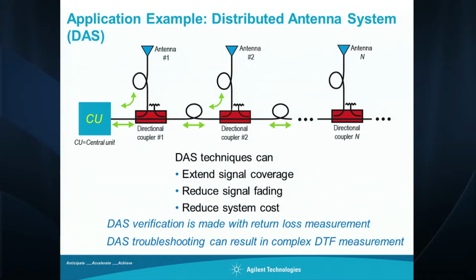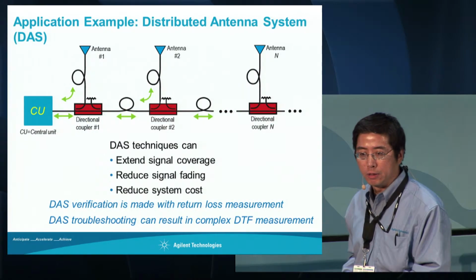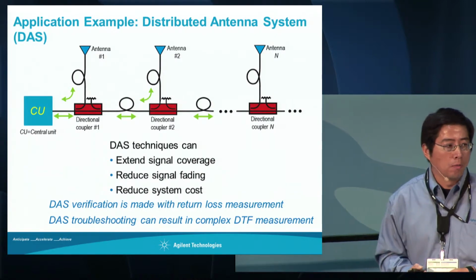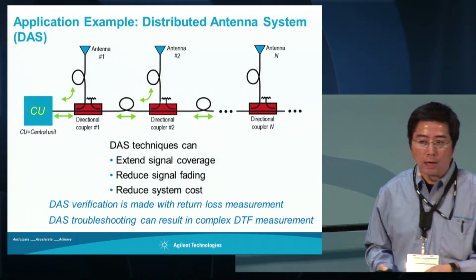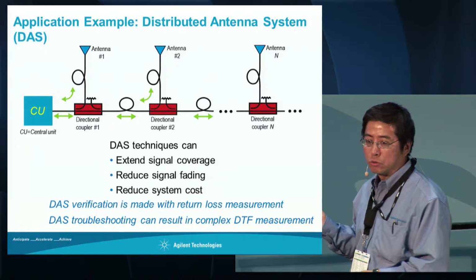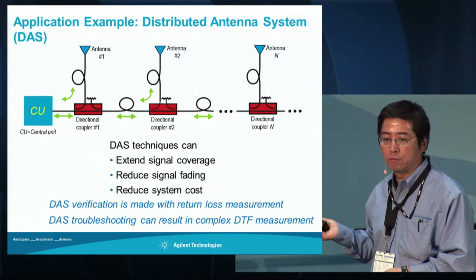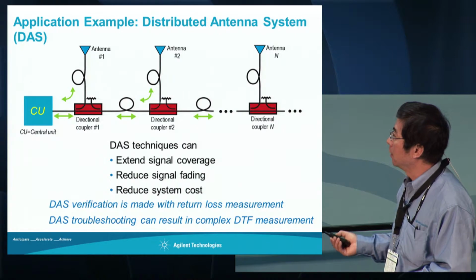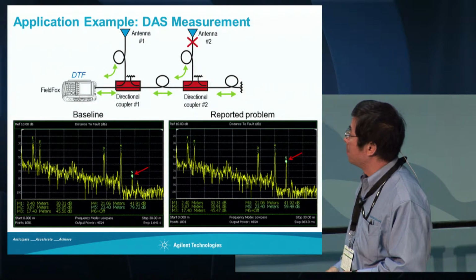You don't want to use one antenna just blasting everywhere, where you get all the reflection. You're not going to get a good service. And so people start to use very low power transmitters inside the building. And of course, you need cables, adapters, and splitters to distribute the signal. Distance to fault measurement and the return loss are critical here. Distance to fault measurement is a very neat tool to help you identify the problem in that system. So this is a demonstration.